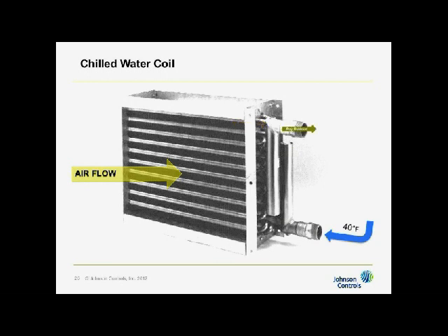How it works is there's, on the other side, in the leaving air side of this coil, in the back where you can't see, I have a temperature sensor that might be set for 55 degrees Fahrenheit. I'll talk all in Fahrenheit, in IP units. The air enters the coil at roughly 80 degrees and leaves about 55, and the water comes out as 56.